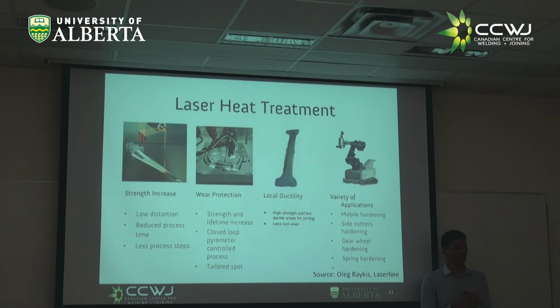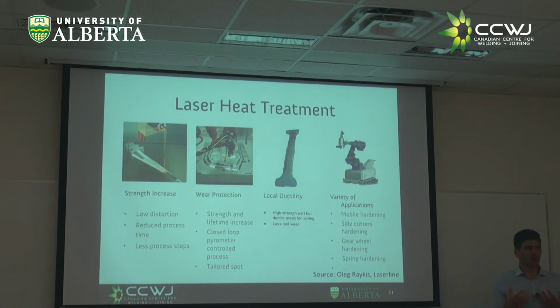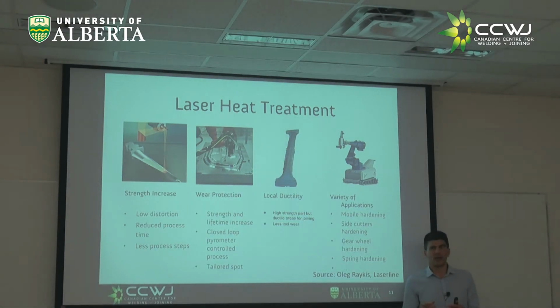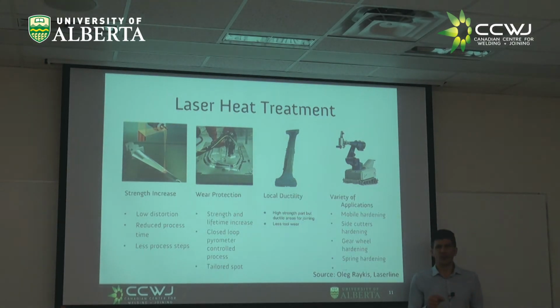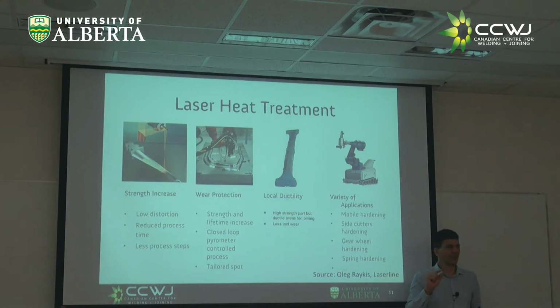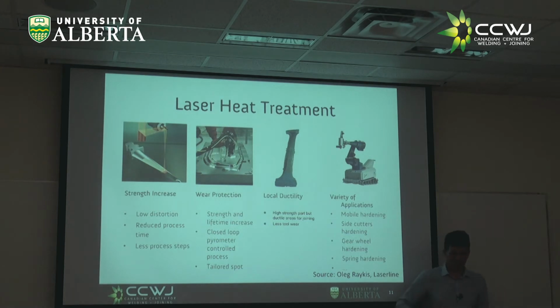Those exact same equations of the semi-infinite solid, and square root of alpha t, that's what governs the laser heat treatment, right? And you can do amazing things because instead of putting things in a furnace and quenching them, now you can do localized heating and quenching. And by tailoring how much power you put and what your travel velocity is, you start tailoring the case depth and the hardness. So all of a sudden, you can make a designer heat treatment, which you cannot when you're just tossing things into a bucket or into a furnace.